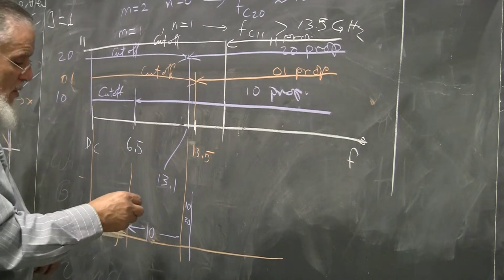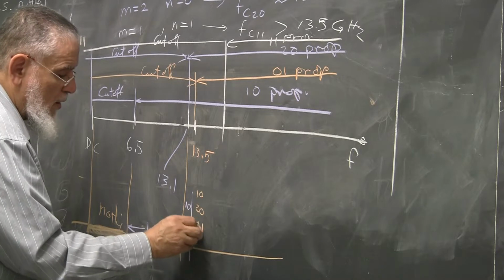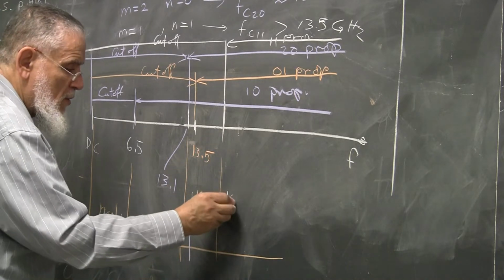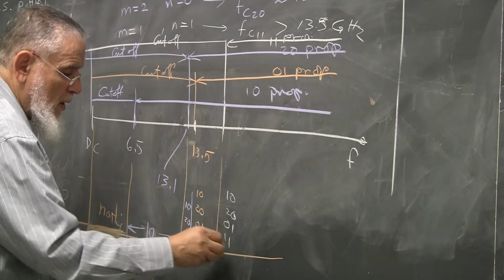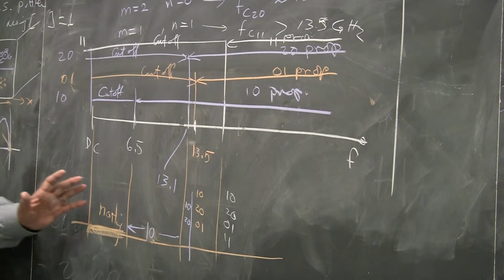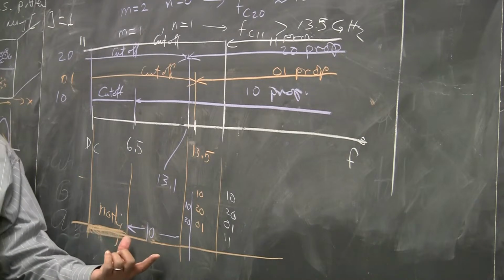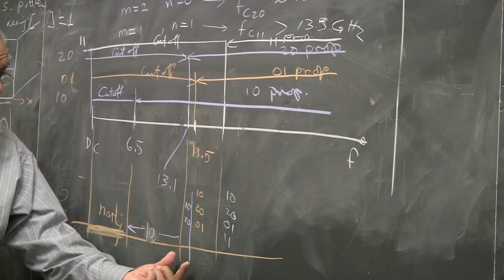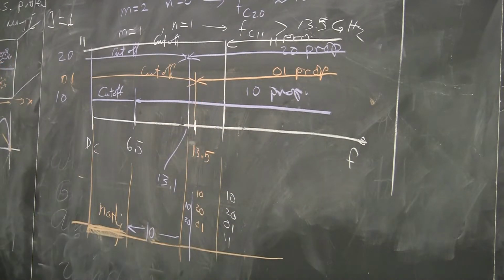Beyond that, you have the 1,0, the 2,0 and the 0,1. Up to here, now you have the 1,0, 2,0, 0,1 and the 1,1. So as you increase your frequency, you're moving from cutoff to what we call a single mode. Here you have 2 modes, 3, 4, and so on and so forth.